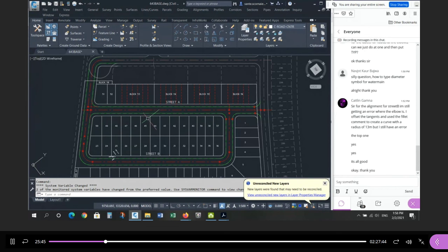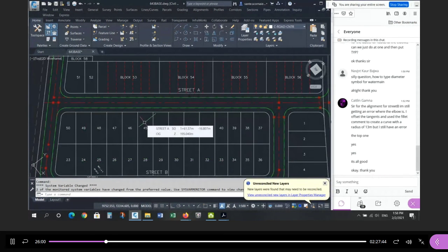Inside the chambers there are valves where you can isolate different parts of the water main, so that if there's a problem with the water main, you can shut off the pipe so that only 20 units are affected at a time, and less than 300 meters. Well, the 300 is probably not going to come into play on this smallest site. So really, the limiting factor is the number of units, which boils down to how many service connections. Not more than 20 can be affected at one time.